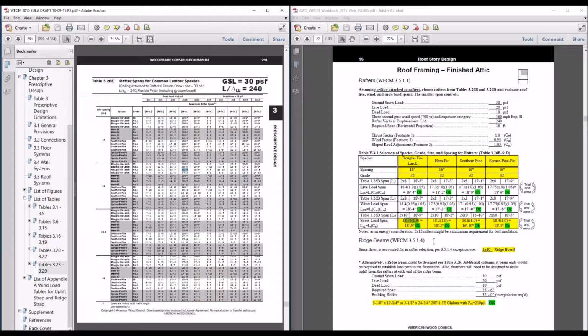We don't have that thrust factor here because this is just a regular ceiling, just has a regular ceiling joist on it. So that span also works, and because we bumped up to a 2x10 back in the workbook, that's what's going to control in this particular application. So note here that 2x12s might be needed for batt insulation, some energy requirements. We're going to see in a second we're going to need it for that vaulted ceiling.